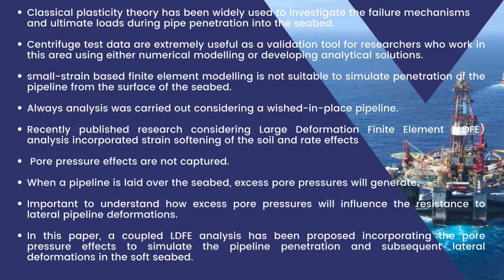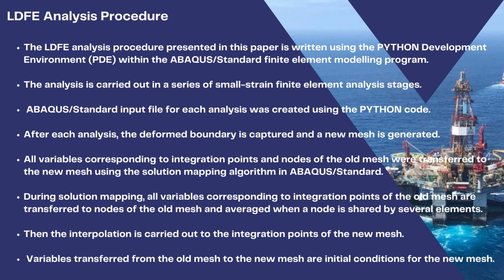Because of that, in this paper, coupled large deformation finite element analysis has been proposed incorporating the pore pressure effects to simulate the pipeline penetration and subsequent lateral deformations in the soft soil. The analysis procedure developed in this paper is written using the Python development environment, which is called PDE, within the Abaqus Standard Finite Element Program.